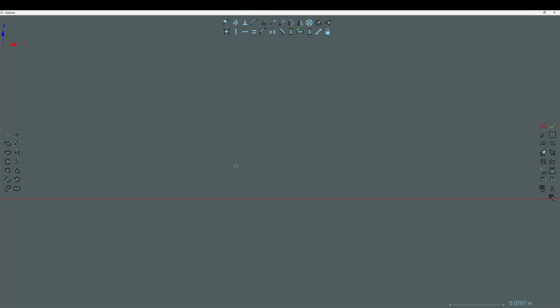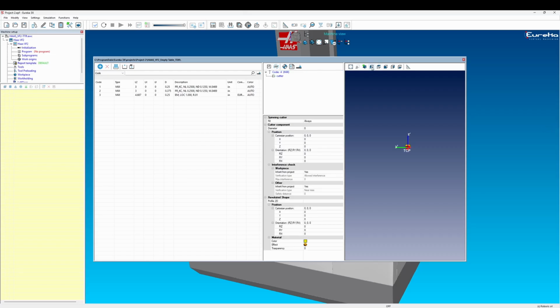Switch back to navigation. The cursor will change to the two circular arrows and reposition the sketch. Go to the right of the sketch window and click the Select button. Then move the dimensions so it's easier to see what they define. Navigate to the green check mark and click it to create the cutter. Click the left view button to zoom in on the cutter.